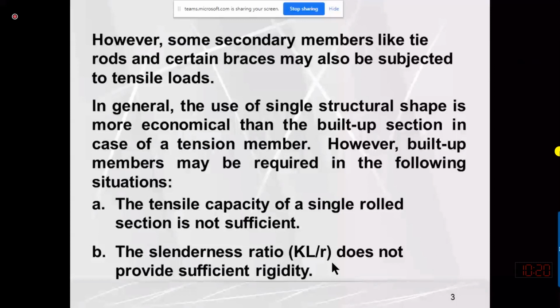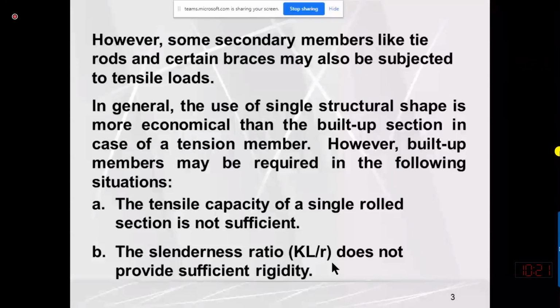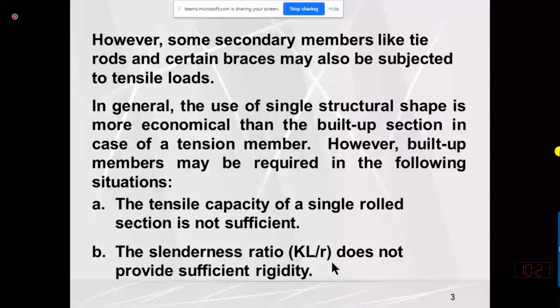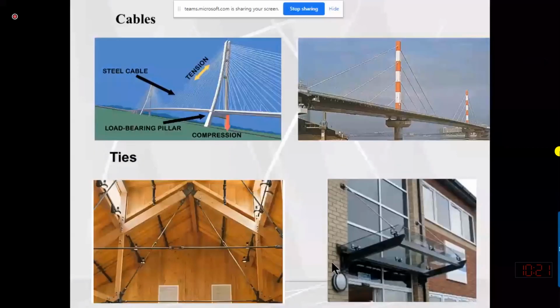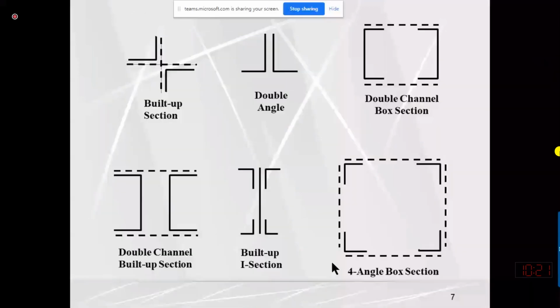Sometimes the applied loads are very small, so just to resist the applied load, we need a very small area. But to satisfy the deflection criteria, we need a larger moment of inertia. A larger moment of inertia is a function of larger depth. So if I select a section whose depth is larger, it will be uneconomical. In that case, we can place the sections sparsely so that we can achieve a larger moment of inertia. I will give you a simple example from this section.